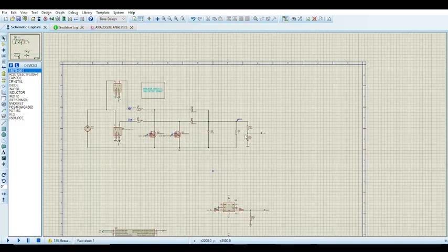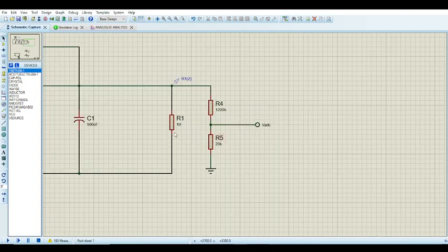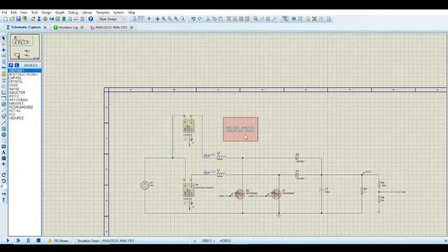So the sensors are very important. You might want to add a voltage follower with an op amp to protect your microcontroller. But sometimes in high speed applications, you want to let go of that op amp and not use it, and just go like this with a capacitor in parallel. But it's your choice.